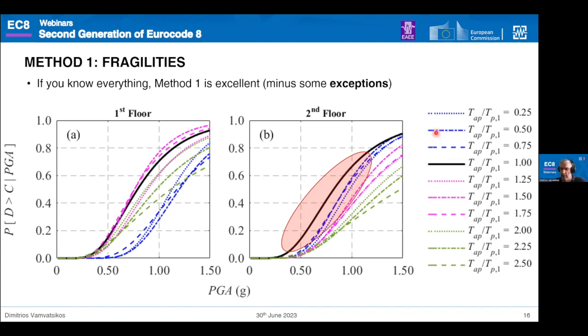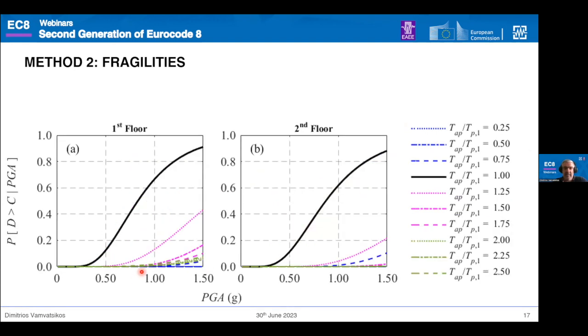When you are outside of resonance, of course, it's a bit more conservative, with an exception of this. Sometimes there are some periods, because of those peaks you saw earlier, that just fluke, rogue wave motions, that you can have some exceedances. But again, you're talking at really high peak ground accelerations of about 1, 1.2. Now, those are large, too large.